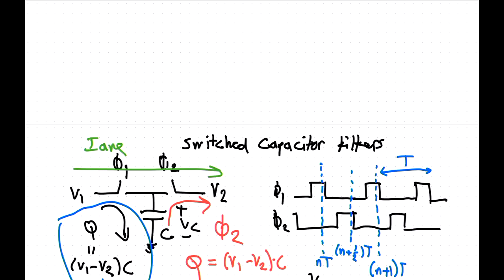At the end of clock phase 2, this capacitor has been connected up to V2. So the voltage across that is V2. Now you connect that via a switch to V1. This has now to charge up to V1. Right? Okay. So how much charge do we need to add to that? That's the voltage change times the value of the capacitance. Okay. Yeah?